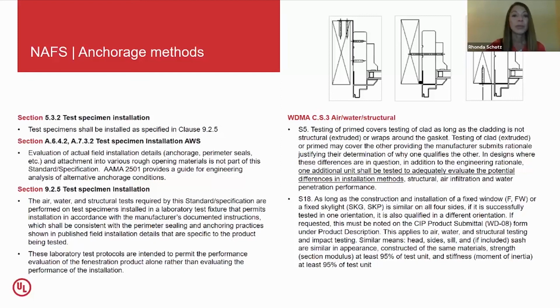Also review WDMA CS3, item S5. In designs where these differences are in question, in addition to the engineering rationale, one additional unit shall be tested to adequately evaluate the potential differences in installation methods for structural, air infiltration, and water penetration performance.